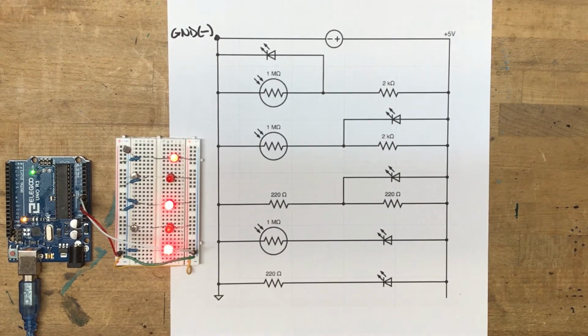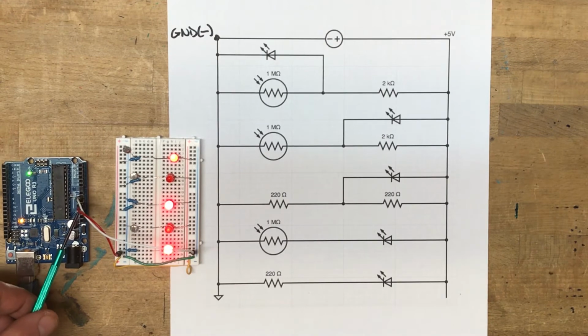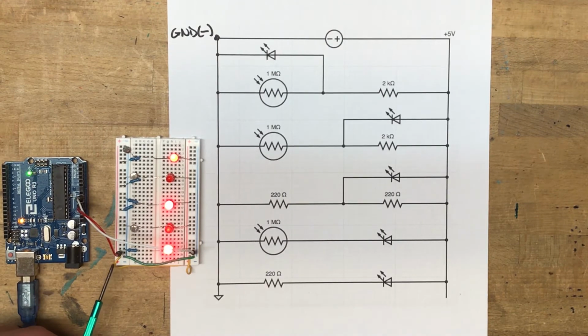So here I've set up a couple of different circuits onto our breadboard. Just to explain what's going on, we're working from the ground and the 5 volt supply on the Arduino and bringing it over to the breadboard. I've jumped the negative to both sides and the positive to both sides with just 2 little pieces of wire, so that all the hots on both sides and all the negatives on both sides are all connected, so it doesn't matter which one they go to.